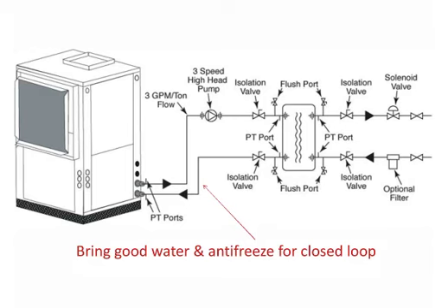with that braze plate. But now what we have, folks, is we have a closed loop between that braze plate and the heat pump. I would suggest that you always make that a little bit of antifreeze, and if you're going to bring it down to 15 degrees protection, don't forget to cut that FP1 jumper that we have, that JW3 on our board. But guys, don't make the mistake of using the well water on site on that closed loop side.